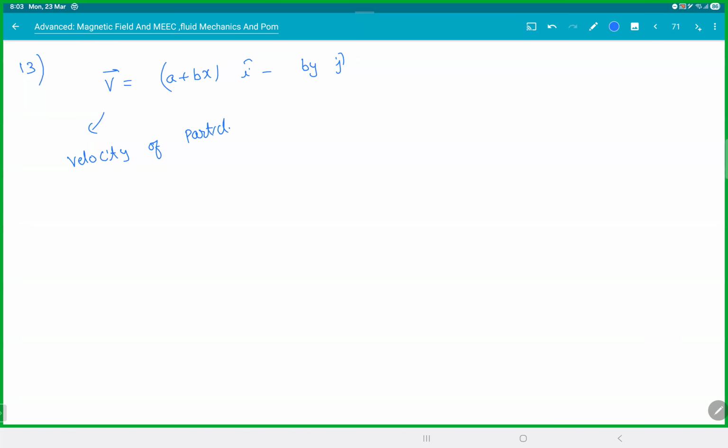Remember, right? What is the streamline? Streamline is the path of the particles. And the velocity of a particle on a streamline is constant with position, meaning at a given position, all the particles that come to that position will have the same velocity. The particle velocity changes with time, but it does not change with position. Can you draw the streamlines? They'll give you 4 pictures and you'll have to fix it.